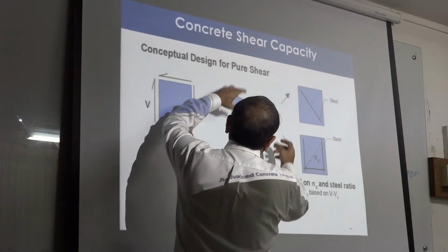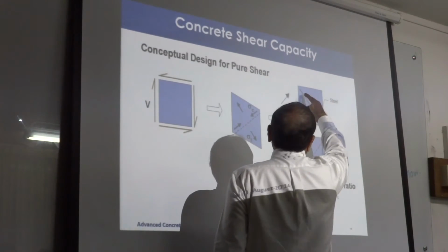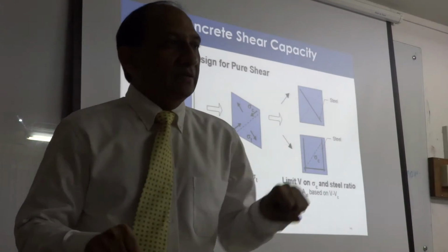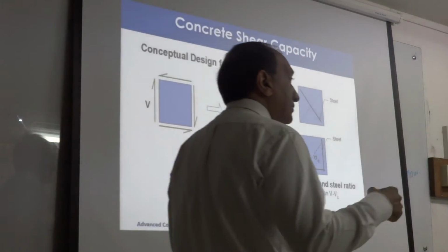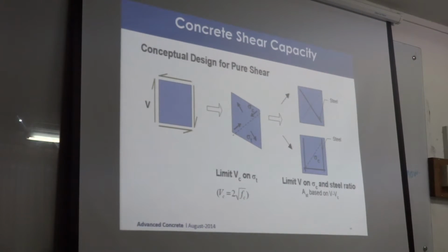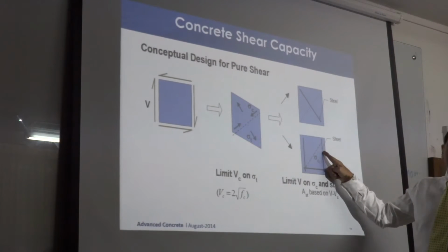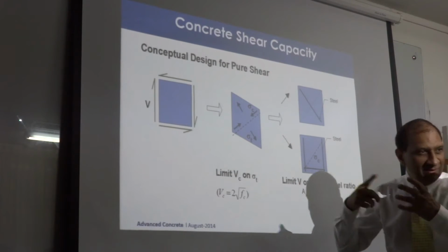Same is the case here. If you have this beam like this, if you apply the load here, it will produce torsion in this beam. If this beam fails in torsion, this will fall down. This load will fall down, correct? Same thing here. If there is a beam here, and this is eccentric, it is going to produce torsion here, right? If it fails, this thing will fall down. These are all called stability torsions. That means if the torsion fails, things will fall down, correct?